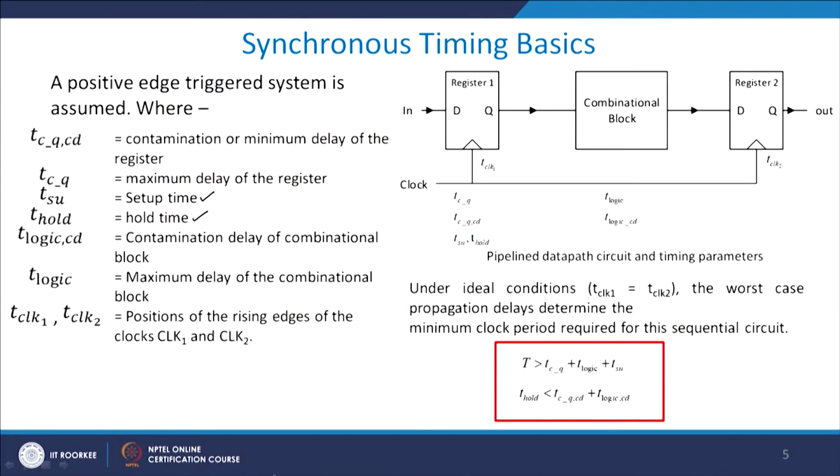Setup time is the minimum time before the rising edge of the clock when your data should remain stable, and hold time is the time after the rising edge of the clock when your data should be stable for proper sampling of the data. This much time you have to give, and it places a restriction on the total frequency of a sequential logic flow.